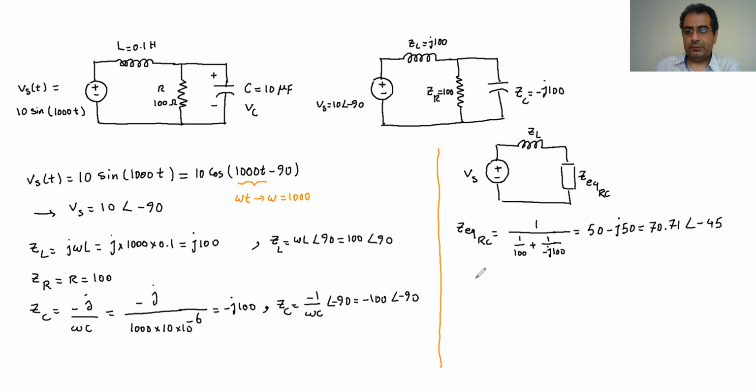And if you remember, this has the voltage of VC, and here is the voltage of VC. The VC is the Vs, because again, assume these are just resistances. So assume this is a resistance, and this is a resistance. This voltage is going to be divided between these two resistances. So how is it going to be divided? In direct relationship with their resistance, if both of them were resistances. So it's going to be the Vs times the ratio of this.